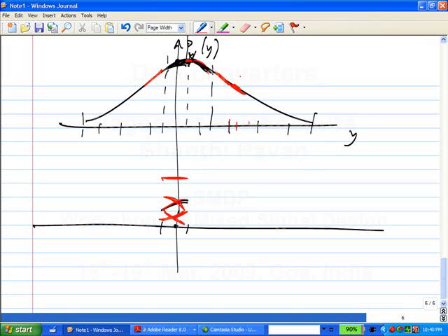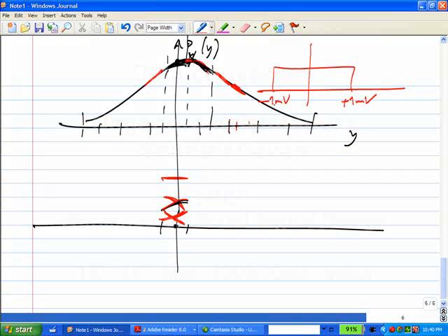Yeah, that's right. That distribution is uniform. It is equally likely to be. So let's say LSB is 2 millivolts. So this is minus 1 millivolt. This is plus 1 millivolt. All I am saying is I am not saying it will be at minus 1 millivolt. I am saying you are equally likely to find it between minus 1 and minus 0.9 millivolts. The likelihood of finding it here and between plus 0.9 and 1 millivolt, all these ranges are the same. That's what uniform distribution means. It doesn't mean it's a constant, right?